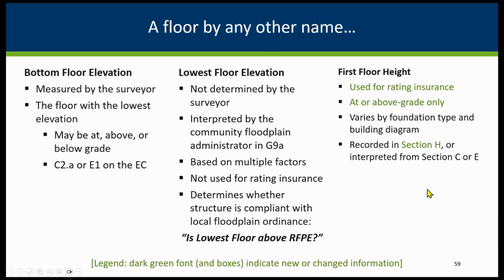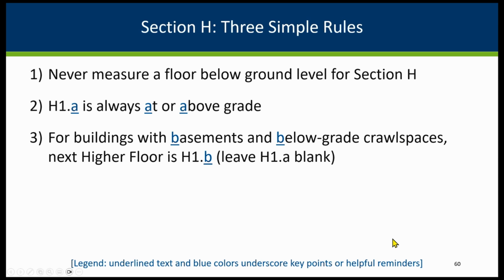Floor by any other name. Now I know Ceil just went through this a moment ago, so just to recap, the bottom floor elevation, that is your C2A. It's going to be measured by your surveyor. That lowest floor elevation is really more for regulatory purposes. And that first floor height, as we're going to be talking about now in Section H, is for insurance purposes. And it does apply to only the at or above grade structures.